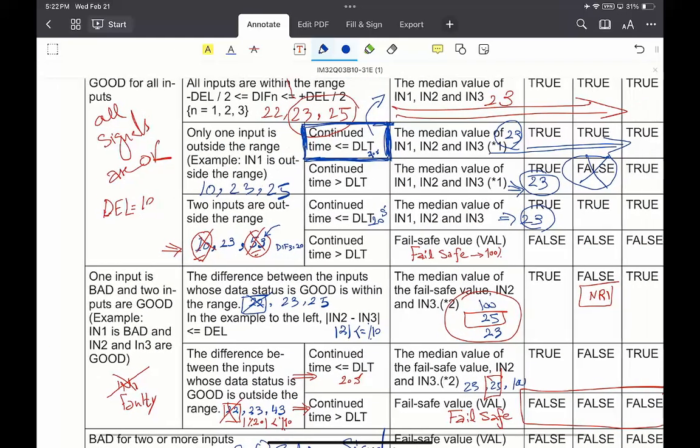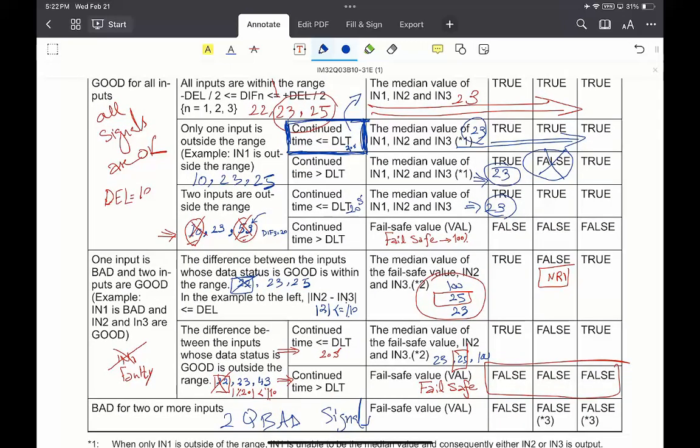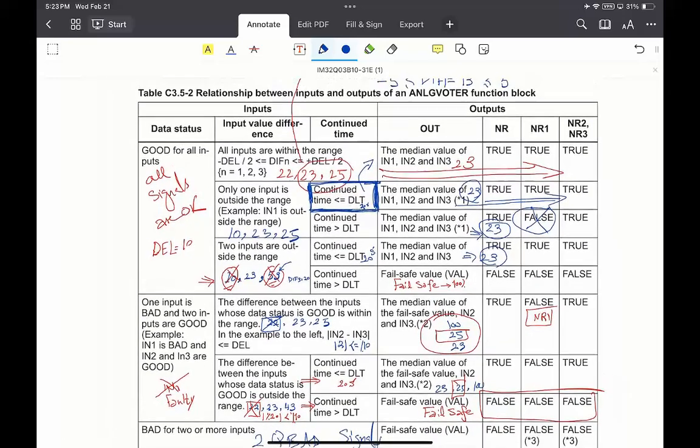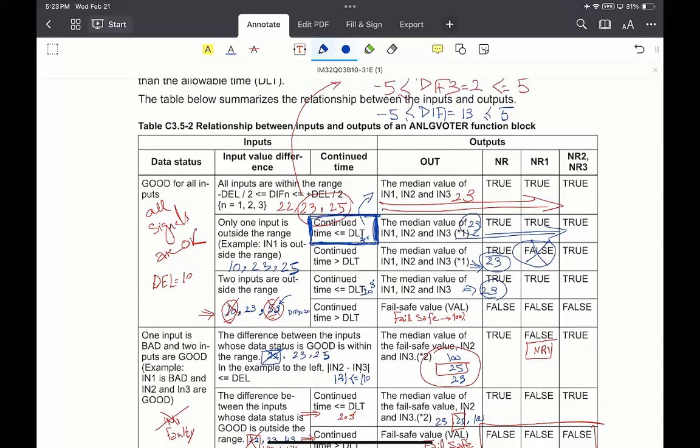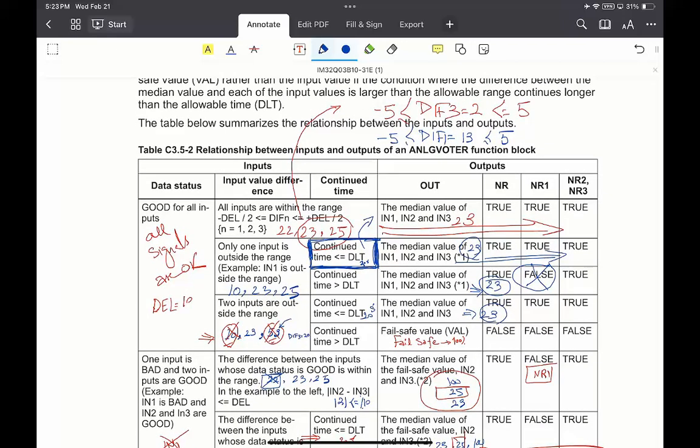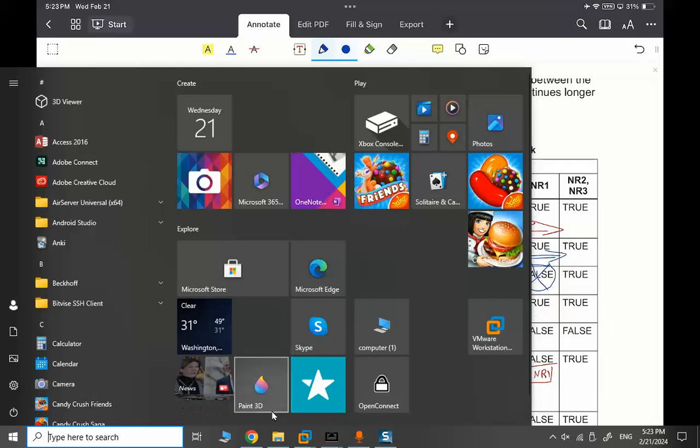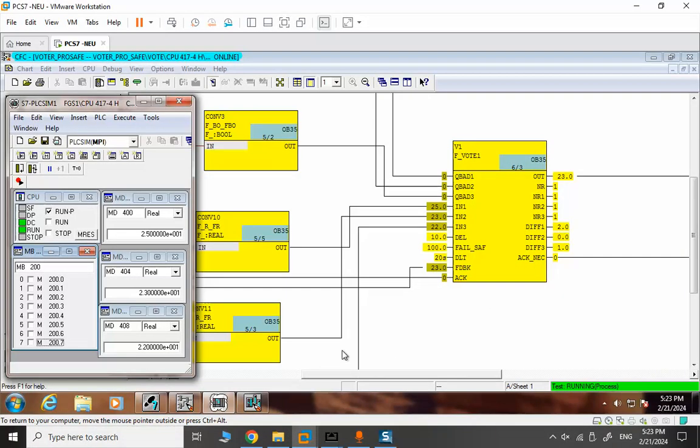So this is a simple, a bit messy chart, like I just added some notes here, but very helpful. We implemented this Yokogawa ProSafe RS voting block in Siemens safety software for HCPU. So I will move to the simulation environment in PC07-8, and we will do some function tests on this logic. So let me just exit this presentation board, and we move to the function block.